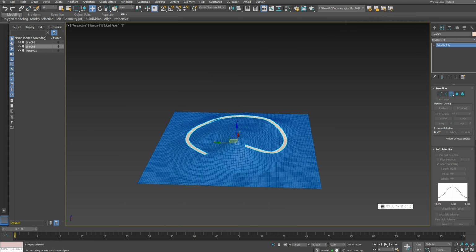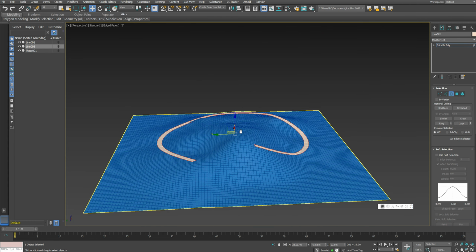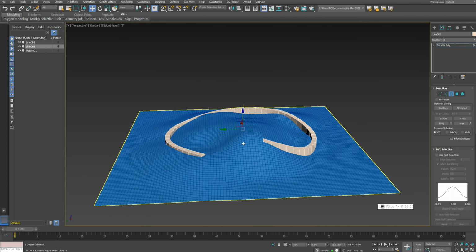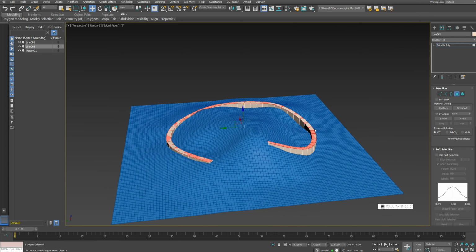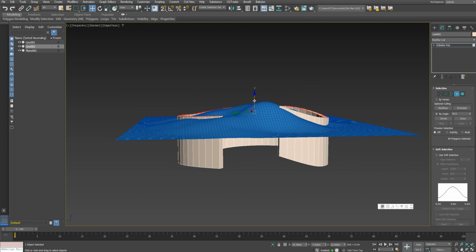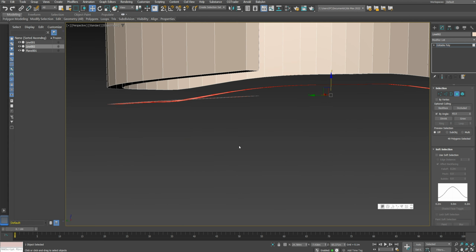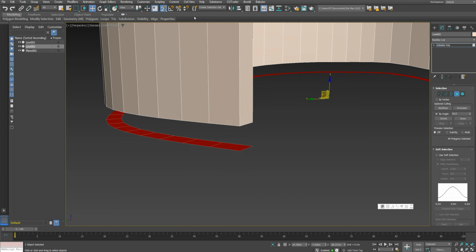Next, we choose the third mode. Box select. Hold down Shift, and drag downwards. Then, we select this face level. Select this face. Hold Ctrl plus Shift to duplicate. After duplicating, let's reverse the normals. 3D snapping. Snap to this point. We perform 3D snapping. Snap onto this face.